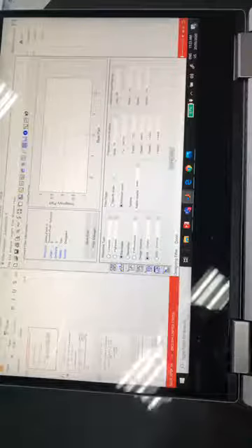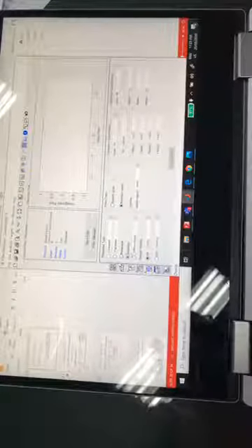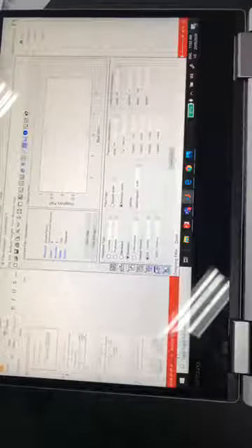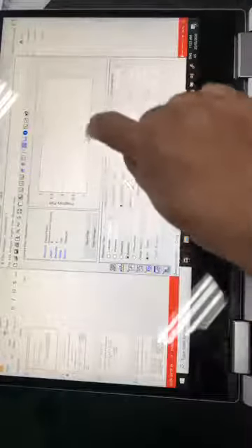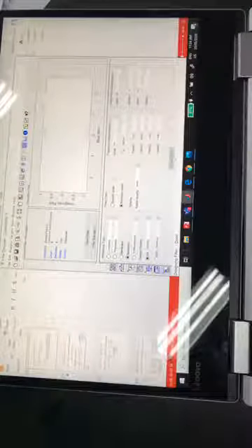What about high pass and band stop? This is interesting. Band stop, you are stopping a band to pass. Obviously the band you intend to stop will have zeros, and the band which you want to let pass, there will be poles.